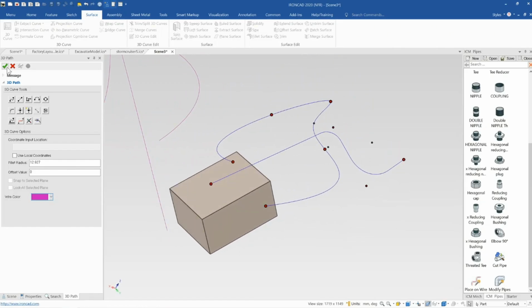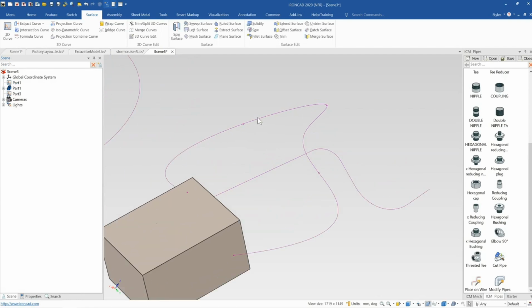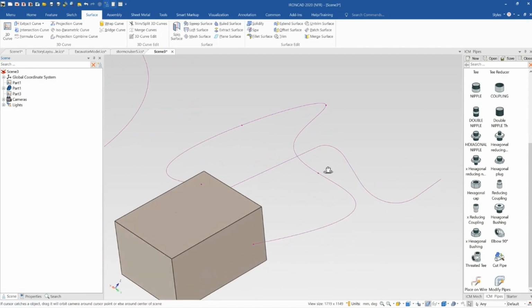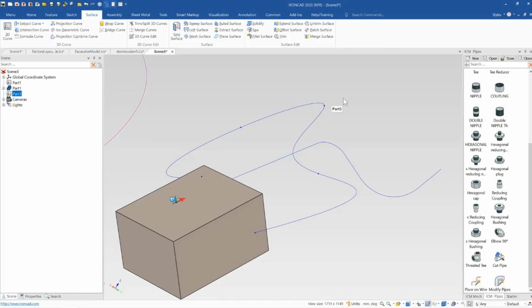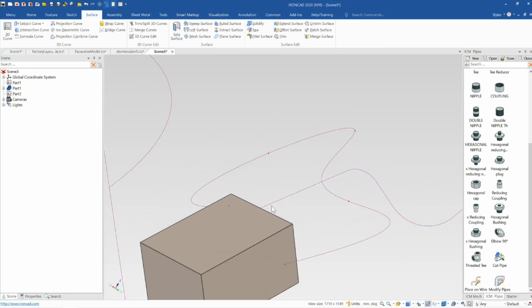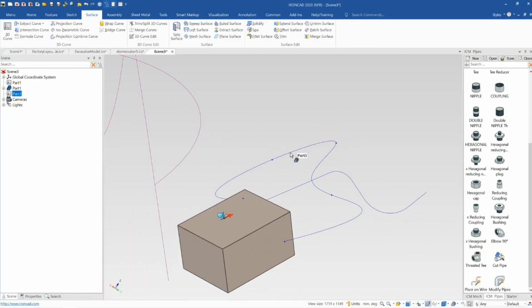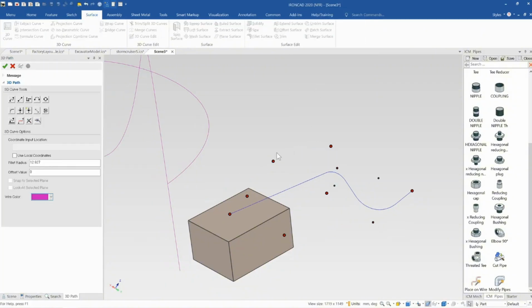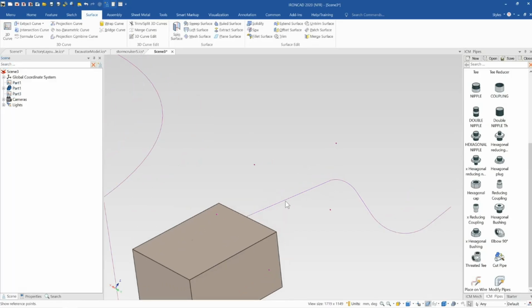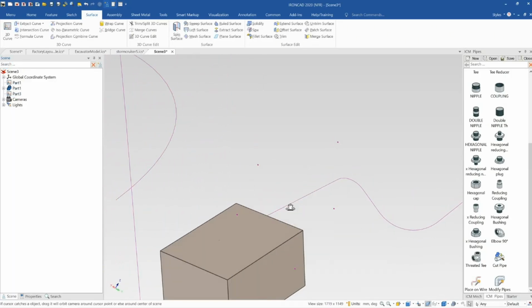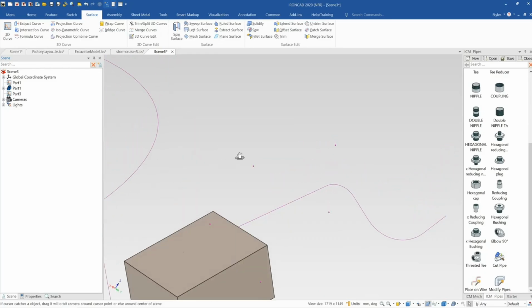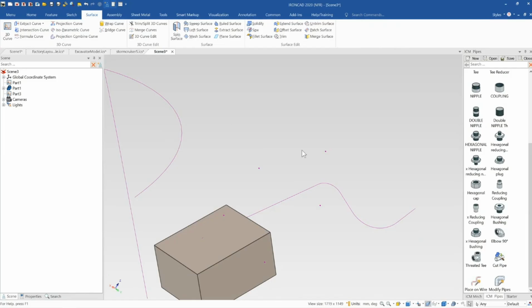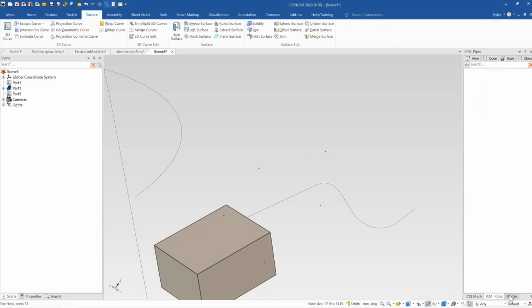And then if we hit OK here, you can see those points are now showing. They're a little bit darker, kind of a point there. And if we create those points by themselves, so if we delete this curve here, and we have that show reference points option checked, they'll show themselves in the 3D scene, which can be useful because you can create these points in the 3D curve command, and then you can use them for snapping things in 3D.